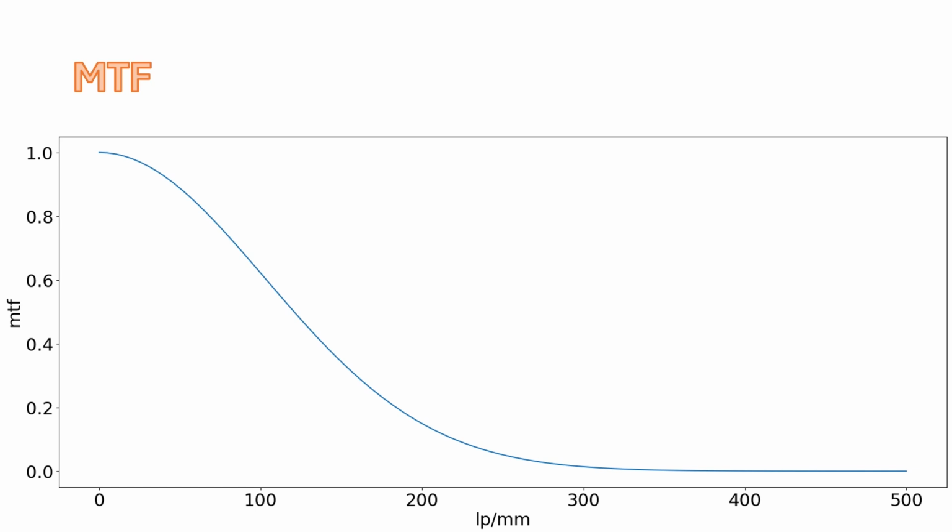2 micron sampling pitch would be the 500 line pairs per millimeter. We're not getting any significant response up to Nyquist, but we are getting some response up to several hundred line pairs per millimeter. But you do see that generally speaking, these systems are potentially a little bit oversampled compared to what would happen at Nyquist.